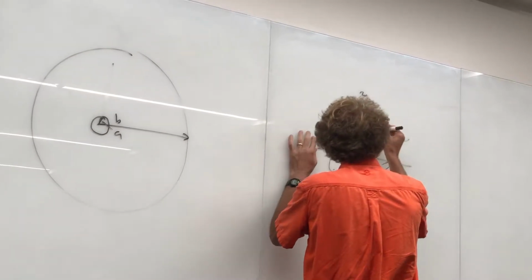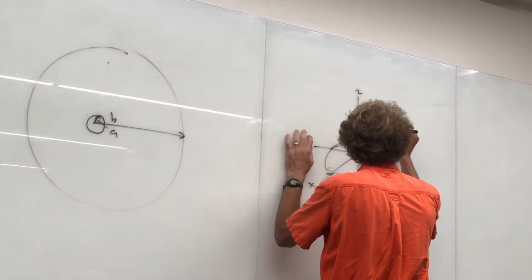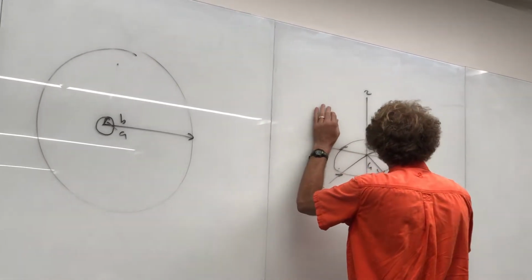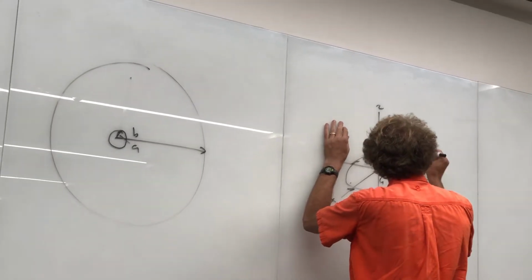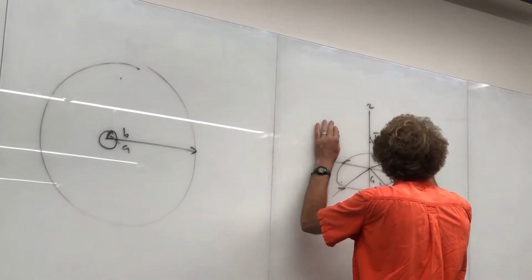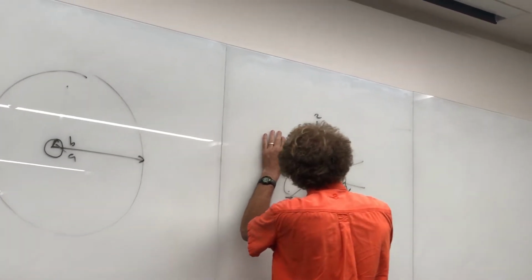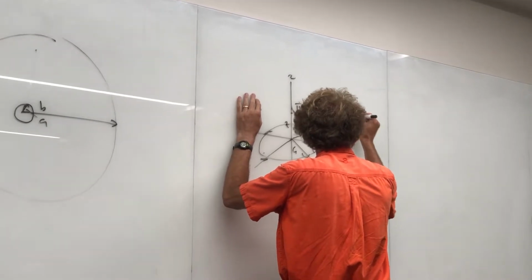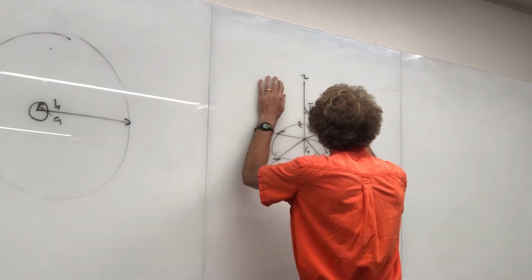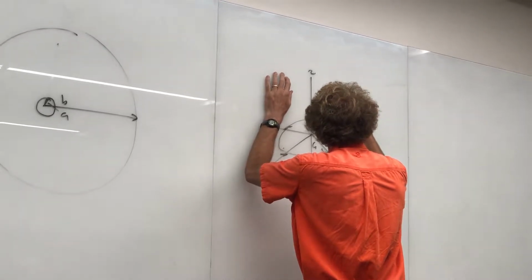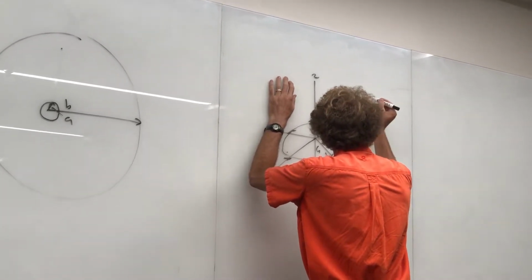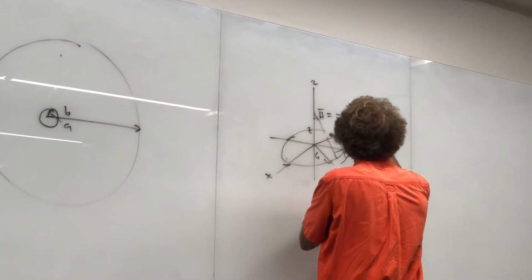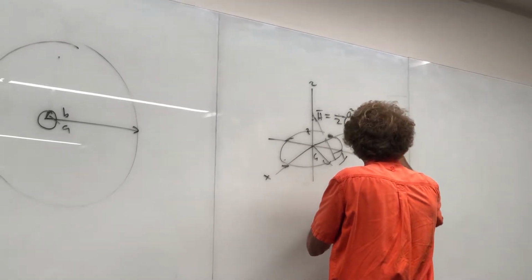You know that on the z-axis, the H field in general is going to be equal to 1 over 2, if that's rho, actually let me do it this way, call this z and a. It's going to be a squared over (a squared plus z squared) to the 3/2 power, times I, in the a_z direction.